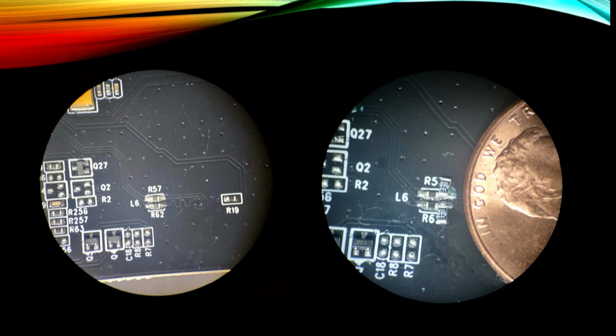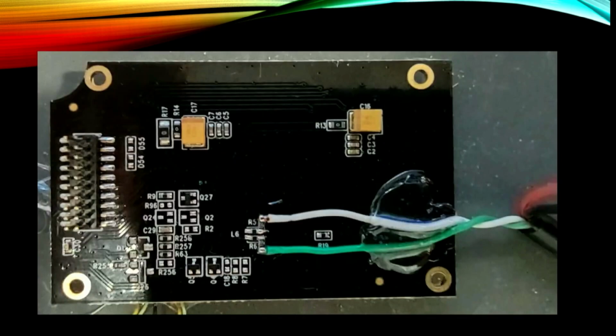I've seen that before. Those resistors measure at 0 ohms. So I'm not sure what their purpose is in this particular case. Maybe it was to just disconnect the circuit altogether at one time, and that was just being used as jumpers. So I added 2 33 ohm resistors in there, and I wired the device up to it, hooked it into my device.